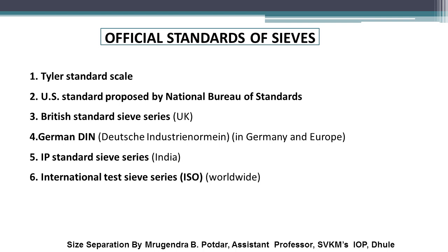These are also known as test sieves. Sieves used for pharmacopoeial testing must match some specifications like number of sieves, nominal mesh aperture, nominal diameter of wire, approximate percentage sieving area, and aperture tolerance average size.